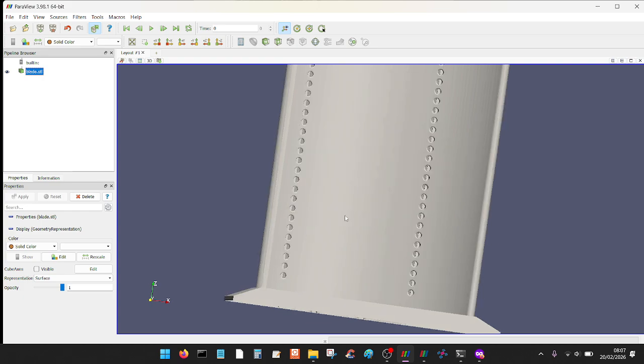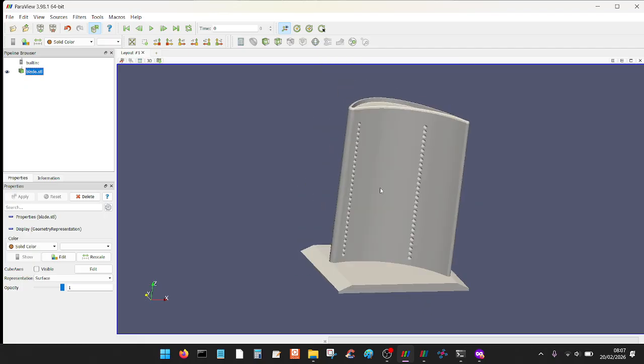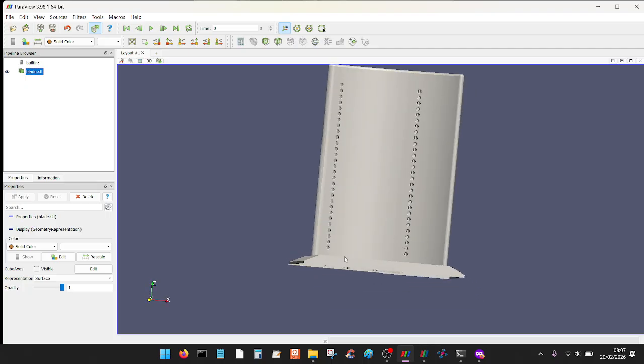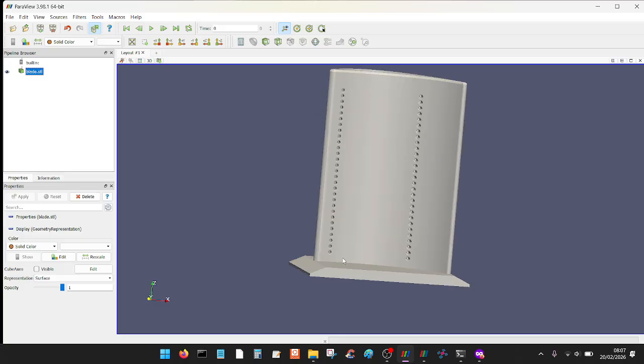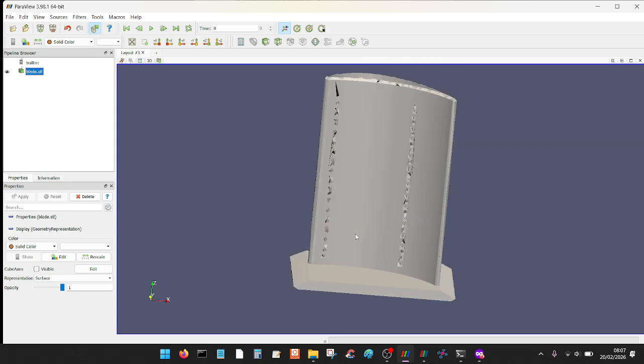When you do blockMesh and then run snappyHexMesh, the faces here will get recognized as part of the outer boundary, so these become Z-min faces, and they also have some Z-min faces either side. Then all I have to do is separate them using topoSet.